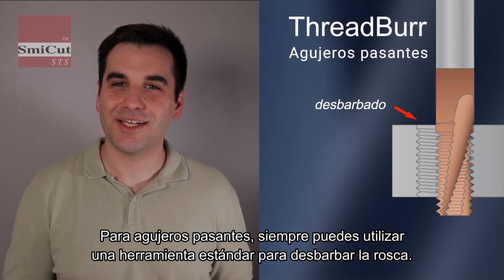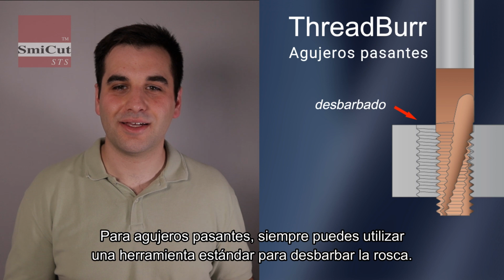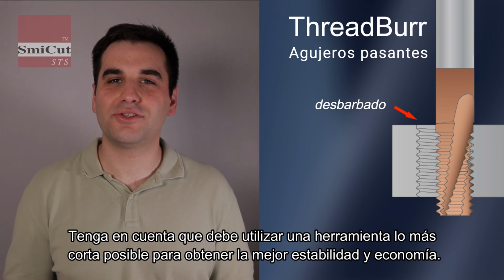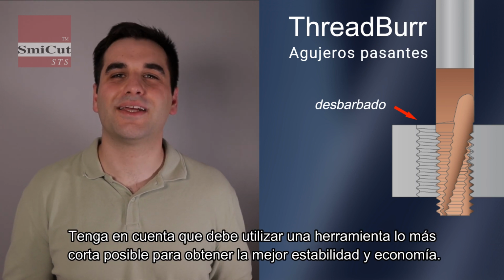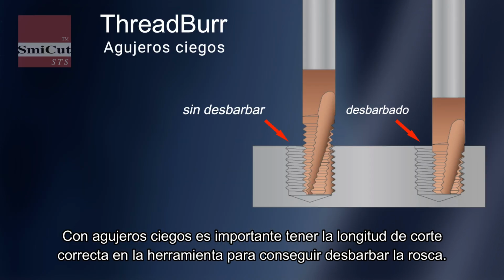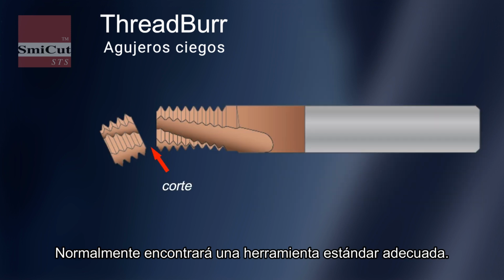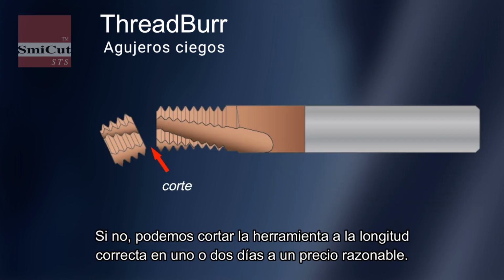For through holes, you can always use a standard tool to get the thread deburred. Please keep in mind you should use a tool as short as possible to get best stability and economy. With blind holes, it is important to have the correct cutting length on the tool to get the thread deburred. Normally, you will find a suitable standard tool. If not, we can cut the tool to the correct length in 1 or 2 days at a reasonable price.